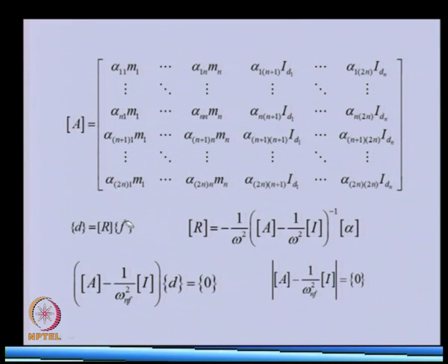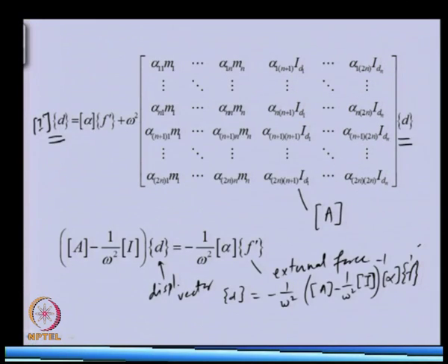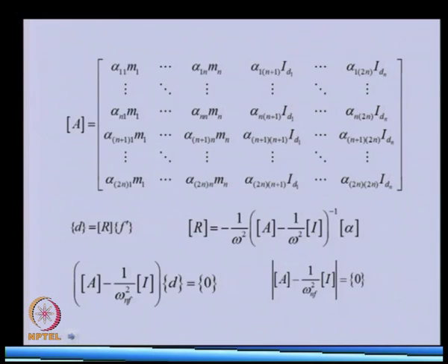So, for various angular speeds, if we know the force values, we can get the displacement, and this is the forced vibration case. Now, if we want to analyze the free vibration, obviously we need to keep the external force equal to 0. So, this whole term will be 0, and we will get this equal to 0, that is this one. So, this is for the free vibration.